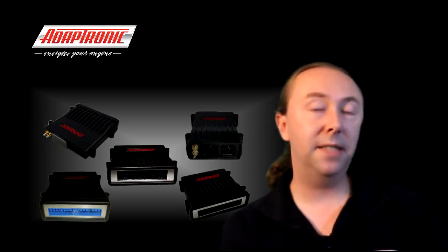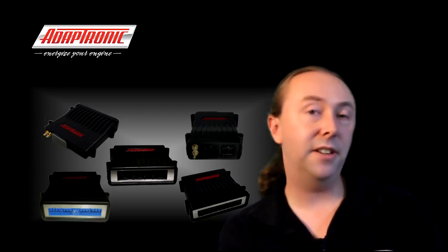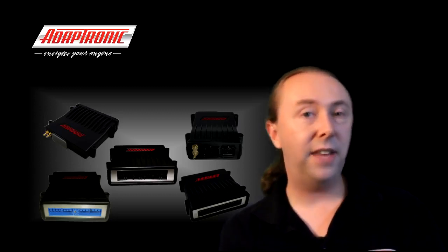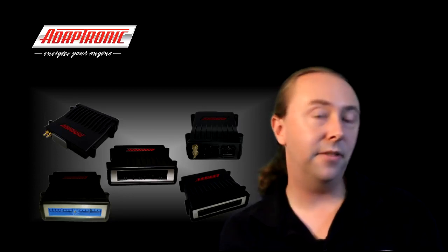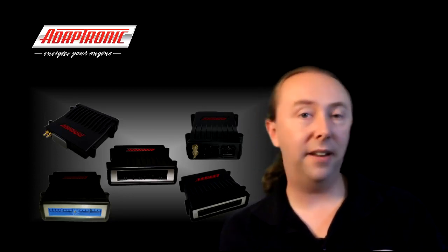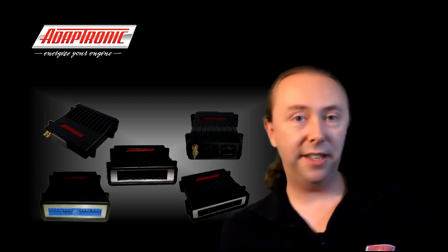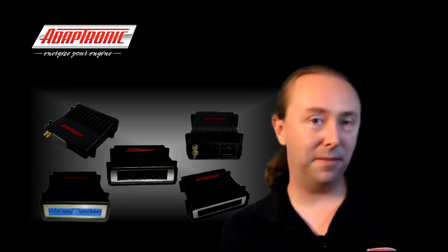As the engine is still spinning down, it hasn't completely stopped yet, the ECU is still tracking the engine rotation, still pulsing in fuel, and at 12 volts now it actually can deliver some fuel. So then when they go to start it after that, some fuel's in there, it fires up and everyone's happy. But it's important to diagnose the problem correctly, otherwise you'll be chasing cranking fuel maps and wondering why you're not getting anywhere.